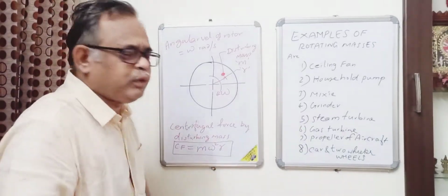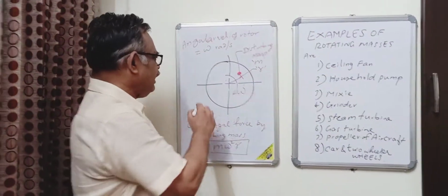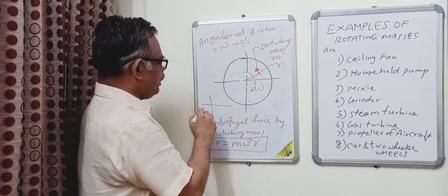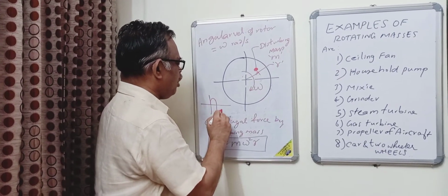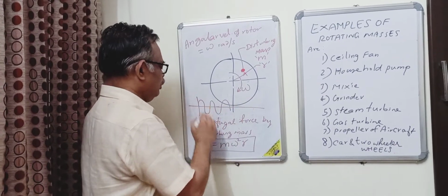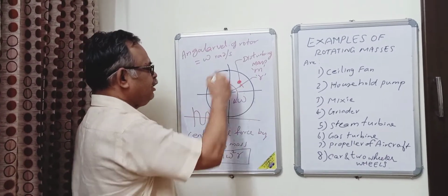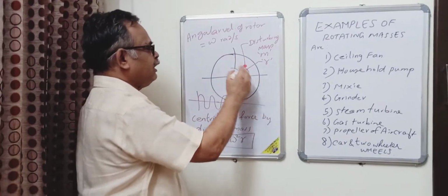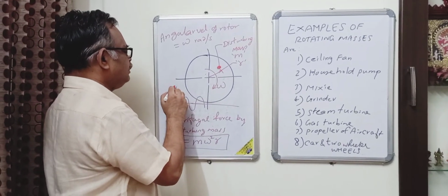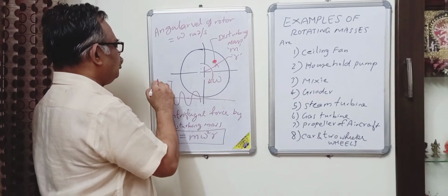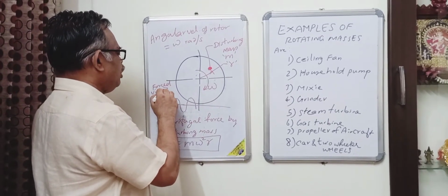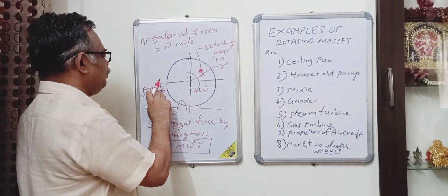As I explained to you in the case of vibration, this centrifugal force will create a periodic forced vibration in the system. As it goes on rotating and acts in a particular direction, it will create a forced vibration like this.